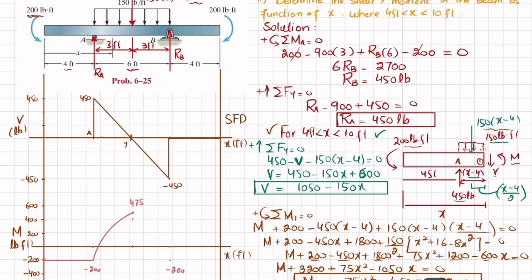And you can see that this shear force is again a straight line with slope decreasing. So the bending moment will be a second degree curve and it will be in clockwise direction. So we will join the same thing like this. It will be like this in curve form. Okay. Now there is no moment from point B till the end. So it will be a straight line.